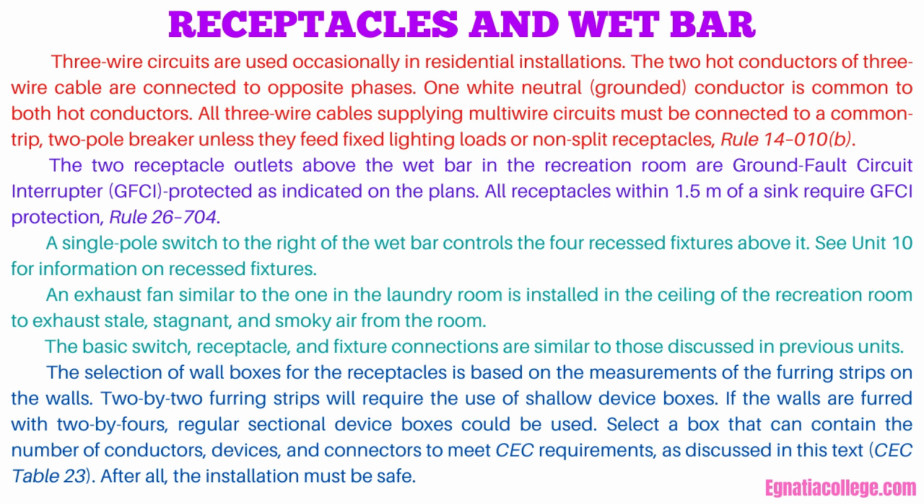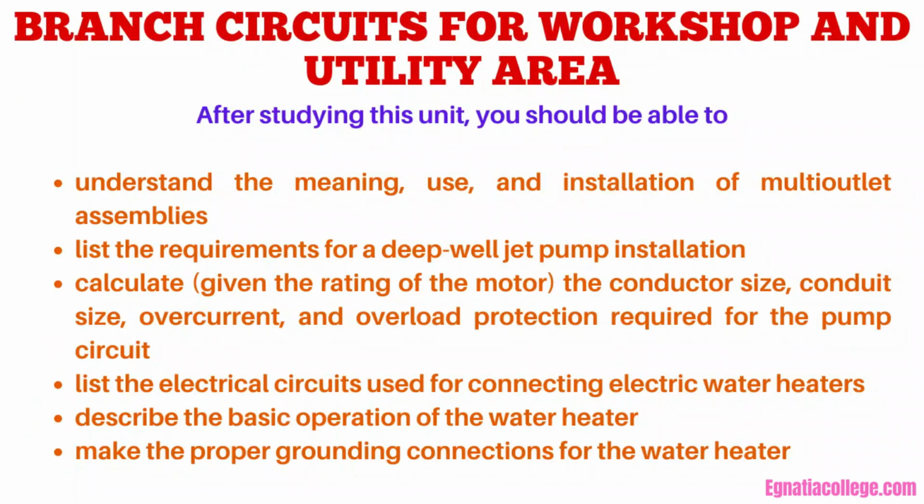Select a box that can contain the number of conductors, devices, and connectors to meet CEC requirements, as discussed in this text, CEC Table 23. After all, the installation must be safe. Branch circuits for workshop and utility area.